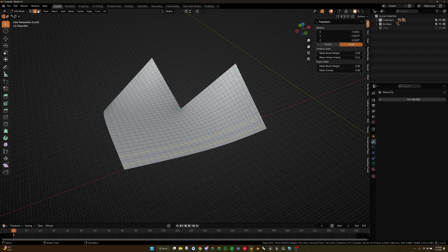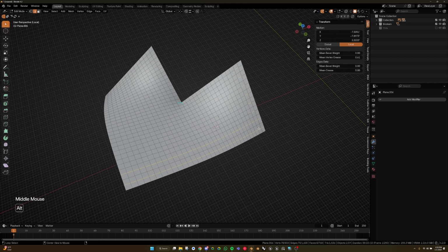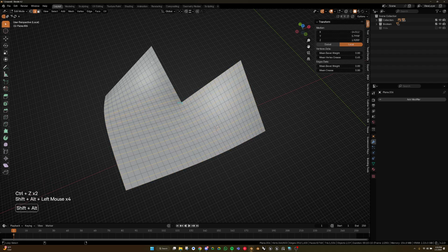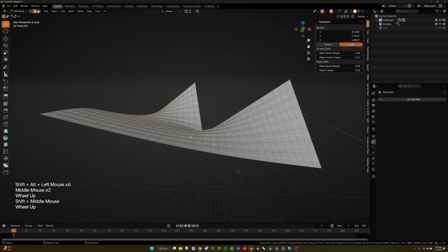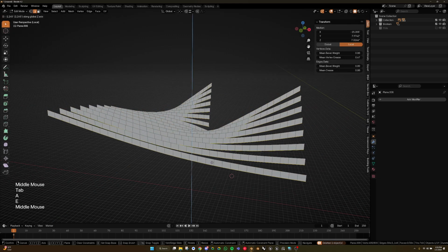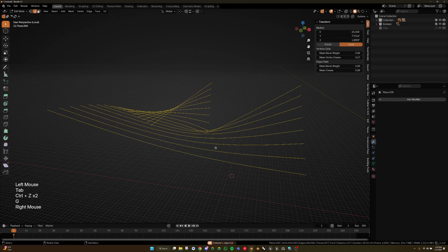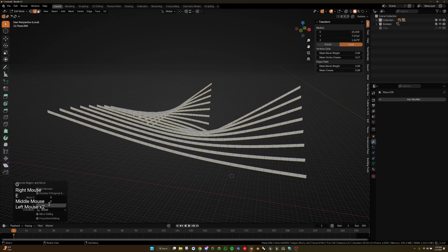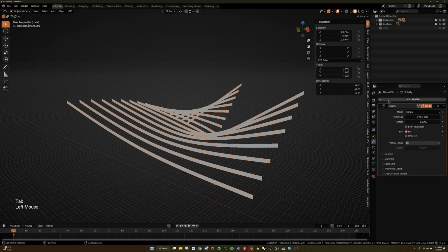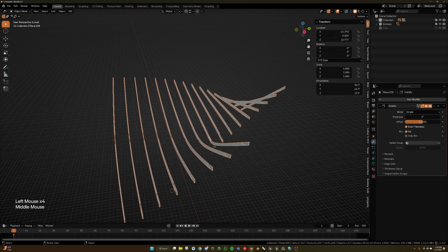I'm just gonna manually do it. And then here to here. Forgot what it was, sorry. Alright. And then separate, and then delete the old mesh. And then extrude this down. Extrude this down by a distance of 8 inches, -8 inches. And then solidify 2 inches, offset even, 0. And there we go. Now it's correct.